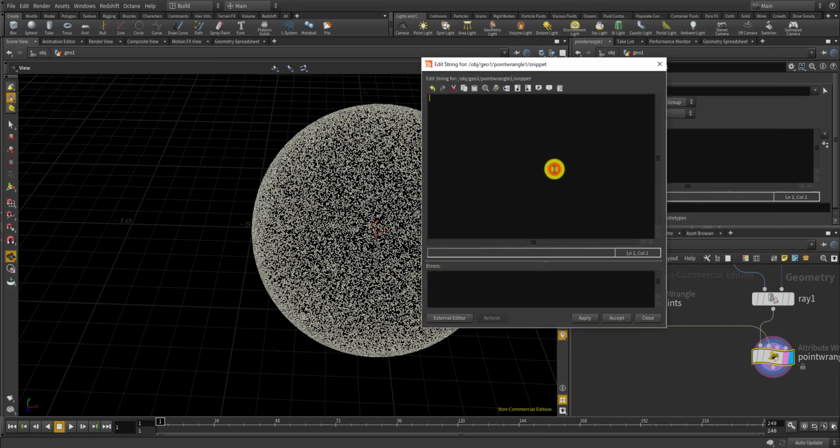Let's write some code here. Okay, let's set the first parameter, float smoothness, chf. This is for the noise function, and float max angle. This is for how much the vector field should rotate using the normal axis. We use the noise function to create an angle and use the angle to rotate the vector field, which comes straight at first. But if it's straight, it's not really natural, so I gotta use some random functions to make it a little bit more natural. Okay, and let's get the near point.